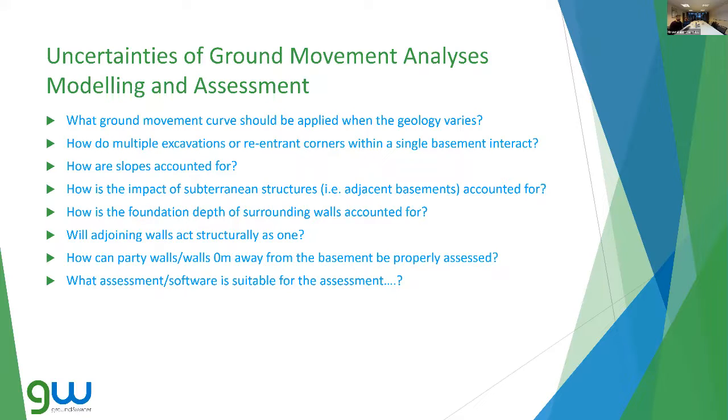Another thing is, how would multiple excavations interact with each other? Or if there's a re-entrant corner within a basement, which is basically if there's an L-shaped section, would there be a lot of settlement because it's away from the two faces of the basement? Will there be a lot of settlement localized to that area? If we do just a standard analysis for that area, would it be over conservative?